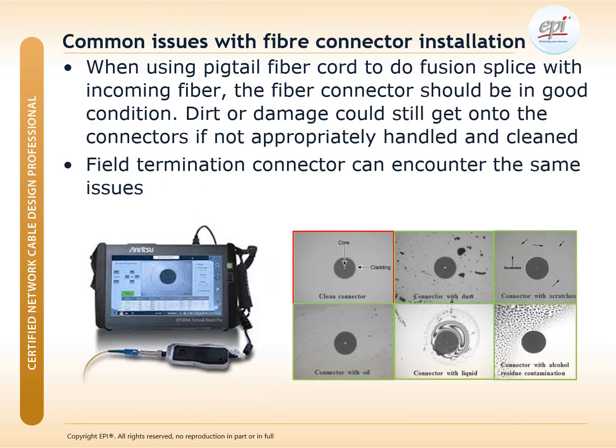On the fiber side, for the fiber connector, before they go into the installation, we need to do the inspection to ensure the fiber connector is in good condition. So these are the common issues, say too much oil, grease on it, dirt or cracked fiber. So if the connector is seriously damaged, then we need to replace it. Of course, if there is grease or dirt on it, then we can clean it, and then we can keep the connector to be used.